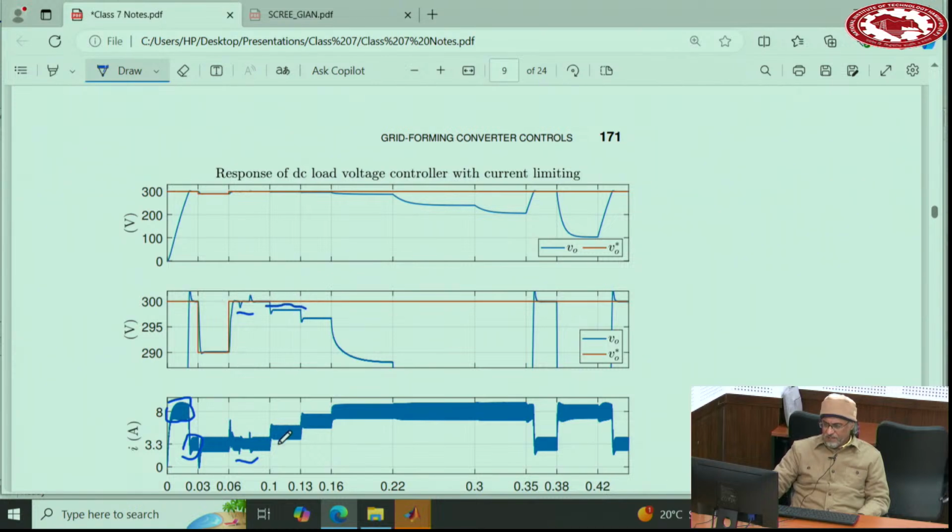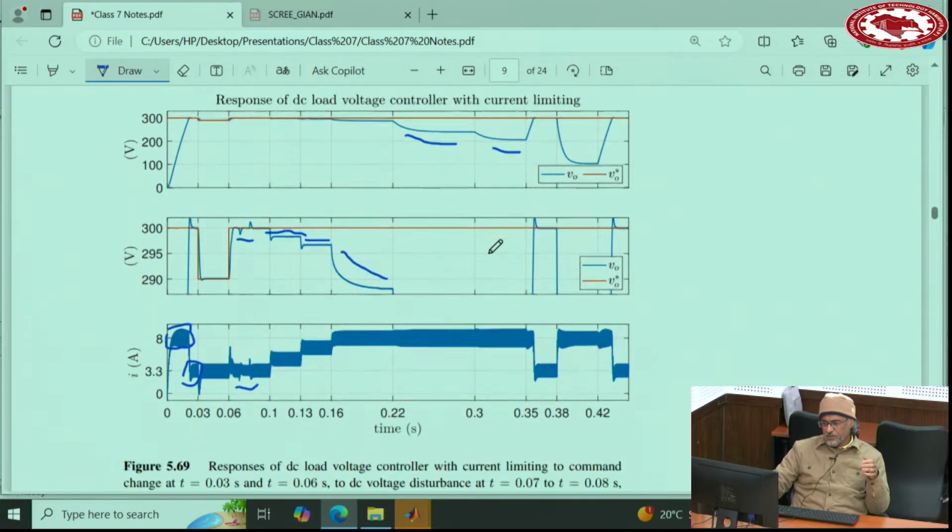See? And then you increase it again, it drops. Now you increase it such that it goes to the current limiting mode, right? So when it goes to current limiting mode, it cannot feed the current that the load requires to keep the voltage. So the voltage drops more. So in that extreme situation, when the load is large, but the converter is not allowed to provide that current, the voltage significantly drops, is this one. And this is even more significant scenario. The current still is limited and the voltage drops more. Okay.